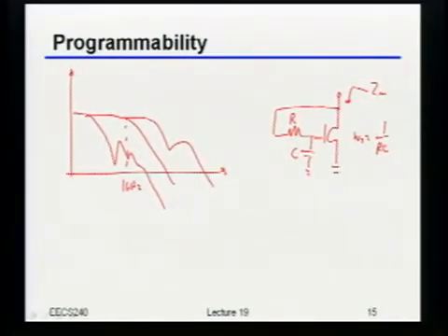Okay, so if that's the frequency of the 0, then if we wanted to be able to tune the location of the 0, that basically means you either need to tune the resistance, tune the capacitance, or both, right?